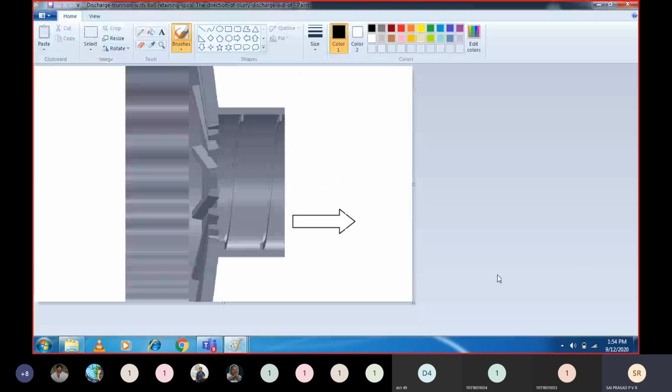Yeah, this is the small part. This is actually the covering of a ball mill. So these plates which are there will be preventing the grinding medium. What is the grinding medium? The spherical ball. So through these gaps, the crushed product will be going out. How does this movement happen? Because you are sending the feed from the left-hand side continuously, because of the displacement, the solid particles will move and try to go away.